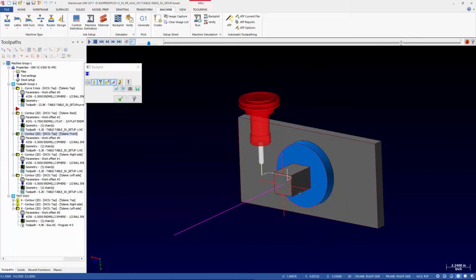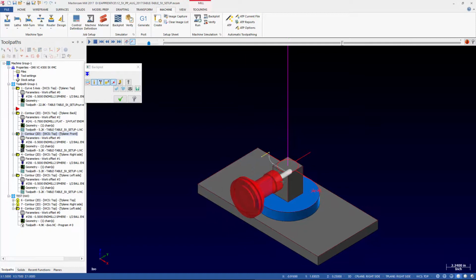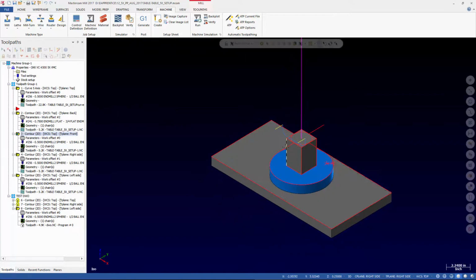Now, there's nothing inherently wrong with that, okay, with that being C180. In fact, for the front plane, that's the proper rotation for this C axis. But if we're just starting out and we throw this path down as our base path, we really have to think about the order in which our tool planes are directing the trunnion to move. Because there's nothing wrong with this being your first toolpath, but just realize that it's going to be at C180. And if you wanted it to be at C0, well, then you should have used this back toolpath.